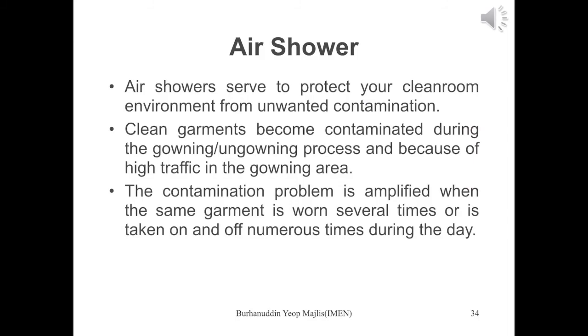Clean garments, for example, become contaminated during the gowning or ungowning process, and because of high traffic in the gowning area, the clean garment is contaminated already. The contamination problem is amplified when the same garment is worn several times or is taken on and off numerous times during the day. So when you enter the clean room with the garment, we need to blow off the particles or contaminants on the garment.